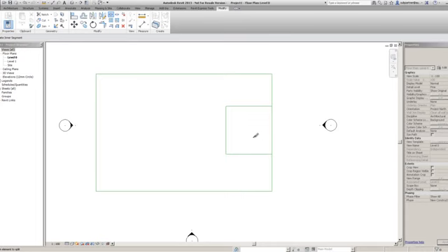Okay, back to where we were. So I've gone split element. Now as I move my mouse away, first thing you'll notice is that my cursor is basically a little scalpel. Nice touch. And what I'm going to do is hover over the object or element, or line in this case, that I want to split, and I'm just going to left click in the middle there. Hit modify, let's see what's going on.